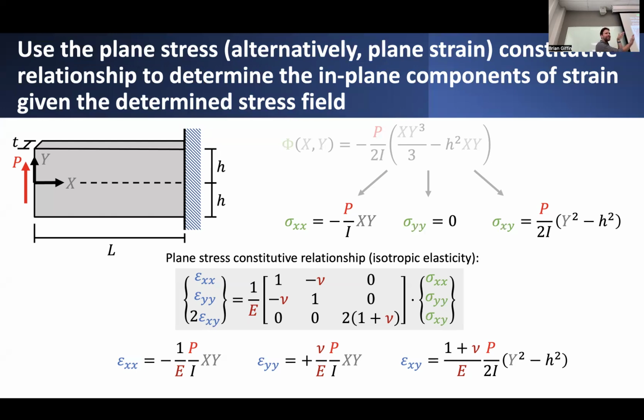If fibers are being compressed axially, then they're also expanding out laterally. And that's all captured within this fully two-dimensional expression for the deformation experienced by small chunks of material anywhere inside of this beam. So we capture all of this interesting phenomena now that we have this theory of elasticity that equips us to analyze and solve these types of problems.